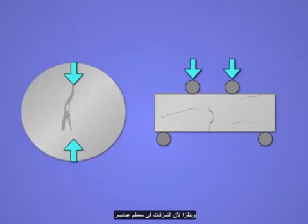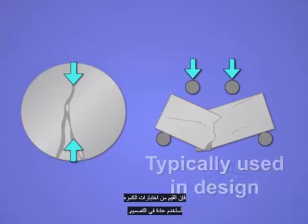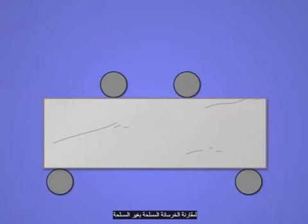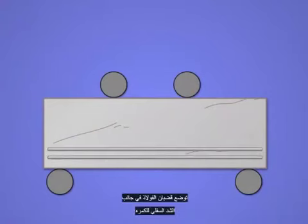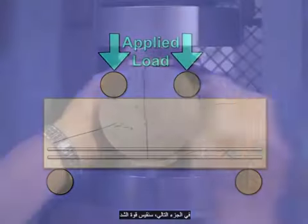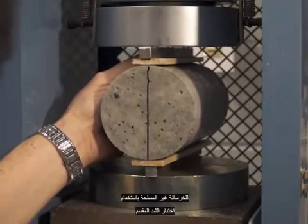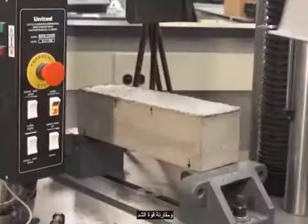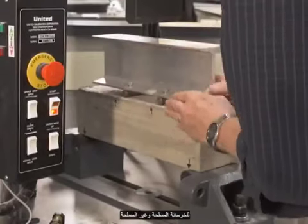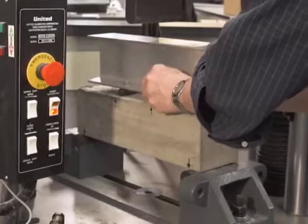But because cracking in many concrete elements is due to flexure, the values from the beam tests are typically used in design. To compare unreinforced to reinforced concrete, steel bars are placed in the bottom tensile side of a beam and then tested. In the next section, we will measure the tensile strength of unreinforced concrete using the split tension test and compare the tensile strength of unreinforced and reinforced concrete using the beam tension test.